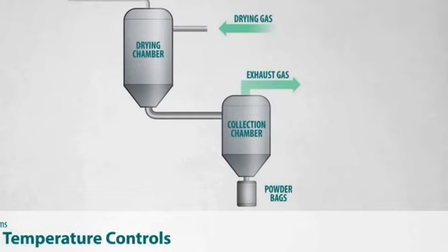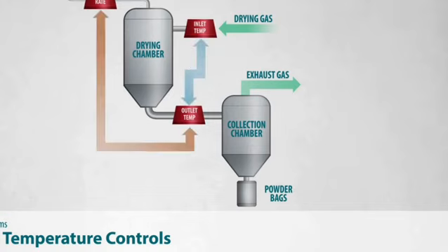Once the droplets are formed, they enter a chamber filled with hot air. The temperature and airflow are carefully controlled. The hot air rapidly evaporates moisture from each droplet, leaving dry particles behind in seconds. This rapid drying helps preserve delicate components like proteins, vitamins, and natural flavors.